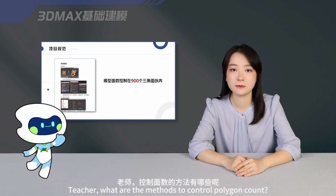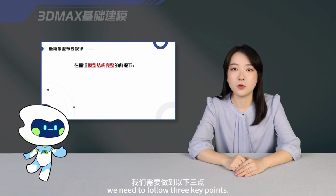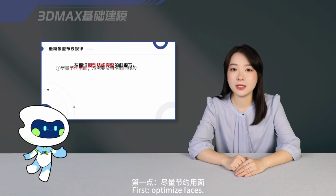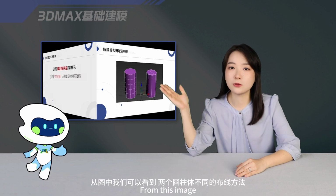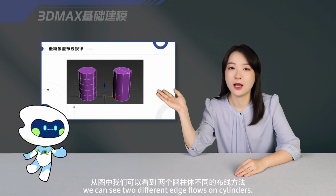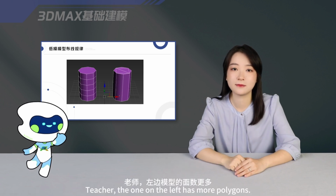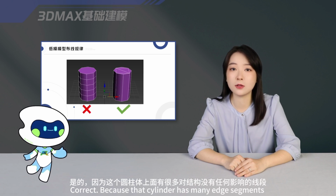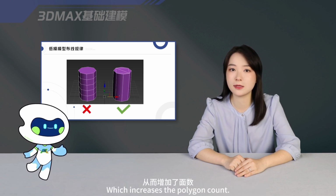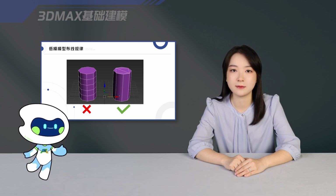Teacher, what are the methods to control polygon count? This brings us to the topology rules for low poly modeling. While keeping the model's structure complete, we need to follow three key points. First, optimize faces. Avoid edge segments that do not contribute to the structure. From this image, we can see two different edge flows on cylinders. Yibao, which cylinder do you think has more polygons? Teacher, the one on the left has more polygons. Correct. Because that cylinder has many edge segments that don't affect the structure, which increases the polygon count. Such unnecessary edge segments should not exist in a low poly model.